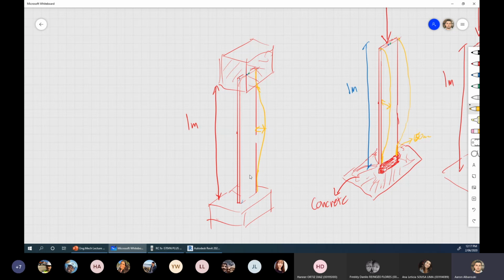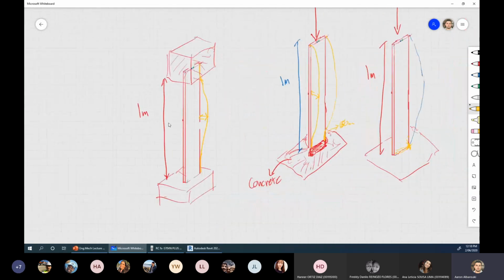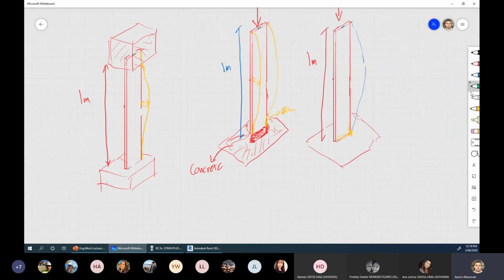This is, guys, what we call the effective length. So what we talked about here, the 3 examples that we looked at, in theory, they are a 1 meter ruler or 1 meter column. So let's forget about rulers now. Let's grow up a bit. Let's talk about columns. If I have 3 different columns, they have the same length, but they have different fixing on the 2 ends. That will determine what we call the effective length. So for this column, let me write them down underneath the columns. For this example, L equals 1 meter, and LE is exactly the same, nothing changed, 1 meter.